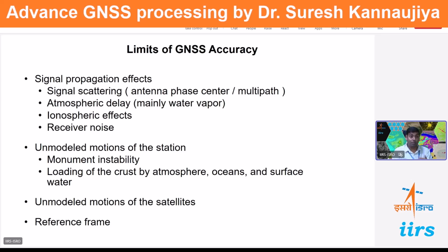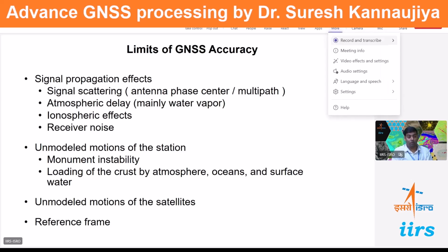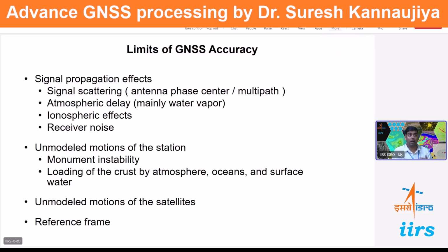And we need to set up the reference system also, because as I told you, there are different reference systems like ITRF, WGS 84, the geocentric datum, and the ellipsoidal model of the Earth. This reference system is not static; it is kinematic. So many models are required to continuously update it. I will give a little overview of this reference system also.